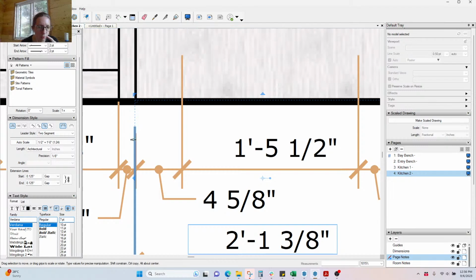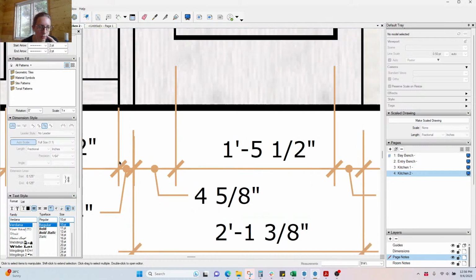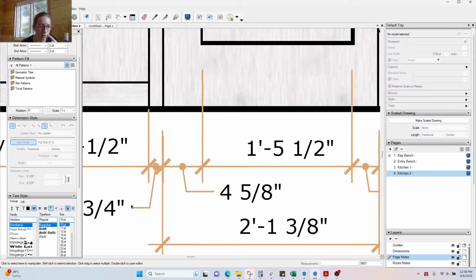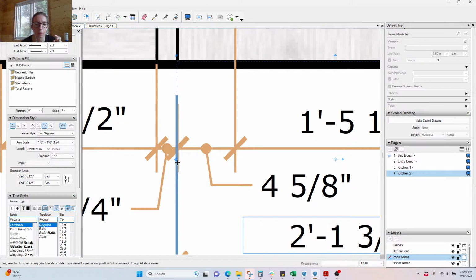And why this is happening is because, as you may or may not have seen earlier, I do have gaps between my drawers and door faces in SketchUp because when I render them, I want that to be shown. But it does cause a bit of a problem with my layout dimensions later on, so I just try to do my best.